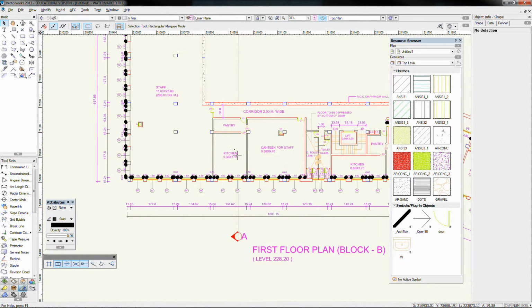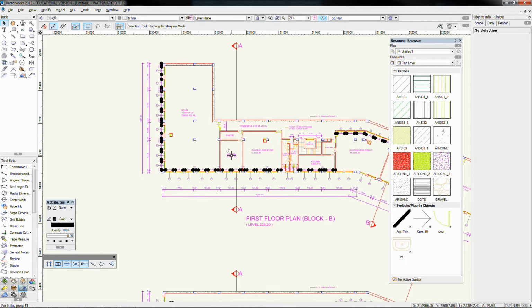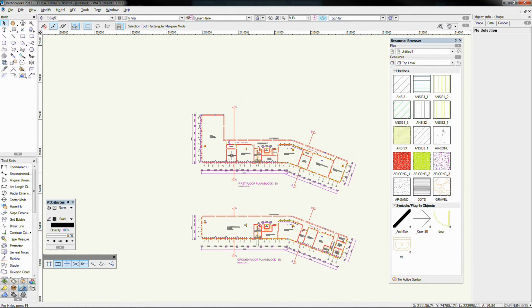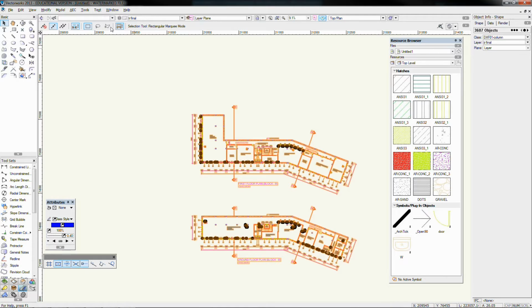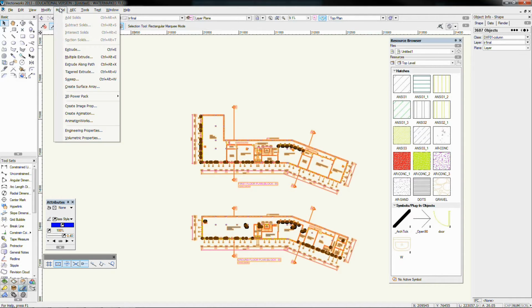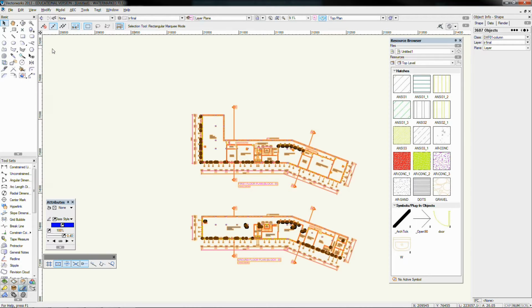So just remembering across that kitchen there, at the moment we've got it as 134.62 millimeters, and it's meant to be 5,300 millimeters. What I'm going to do is just tap X. I'm going to select over everything here. Could have done Control A again for me, and I'm going to go up here to the model. Here we go, modify, sorry, to scale objects, the fifth option down.